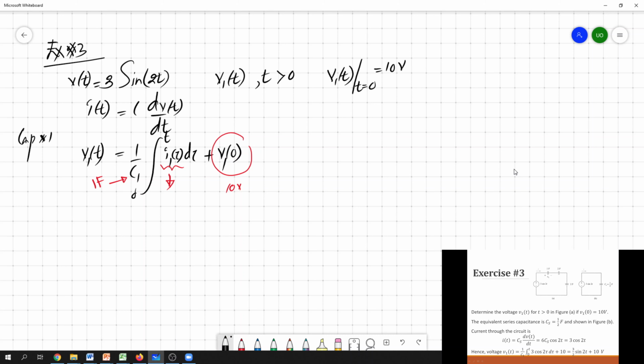By looking at the circuit, we can simply say that the current flow through capacitor 1 is the same as the current flow through capacitors 2 and 3 because they are connected in series. So we can simplify the circuit by combining the series capacitors into a single equivalent capacitor.